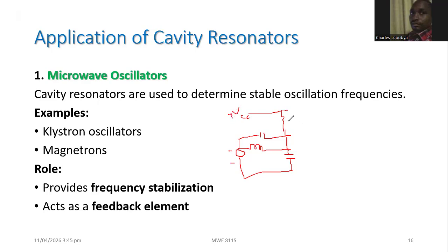You need a positive voltage here. There you need a resistor. Somewhere here you need a transistor to form an oscillator. And of course you have an option to put another capacitor there. So let's call this capacitor C and this one C, which is usually the same value, inductor L there. Then you have a small voltage there. Okay, so this is grounded.